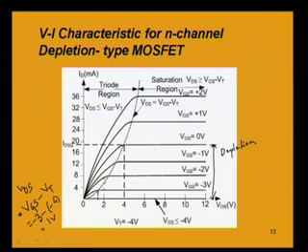If we look into the gap between Vgs 0 volt and Vgs plus 1 volt and the gap between Vgs 0 volt and Vgs minus 1 volt, this gap in the positive direction is much higher. That signifies that the drain to source current is now much higher.